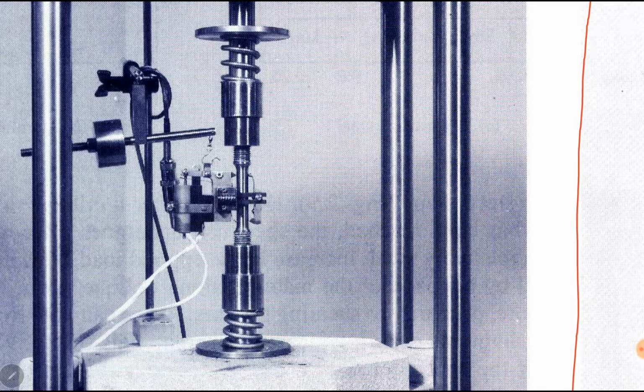Okay, coming back here. Here we can see that in the necking region, the stress is decreasing. Why is it decreasing? We know that stress is equal to force per unit area. While necking, the cross-sectional area decreases gradually. If area is decreasing, the stress must increase.